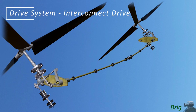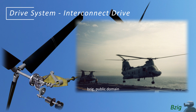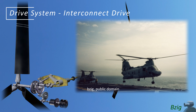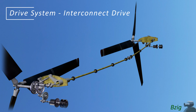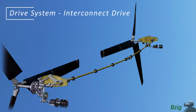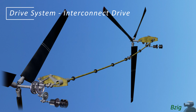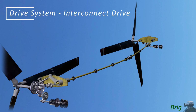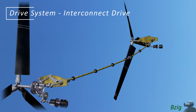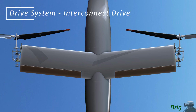That drive shaft also provides mechanical synchronization of the prop rotors. Although, unlike aircraft like the CH-46, tilt rotor blades don't intermesh, so mechanical synchronization isn't critical for safety. In fact, as standalone failures, neither an engine failure nor an interconnect failure are catastrophic. In the presence of either one of those failures, power is still sent to both rotor systems. It's only the combination of those two failures that result in uncontrollable asymmetric thrust.